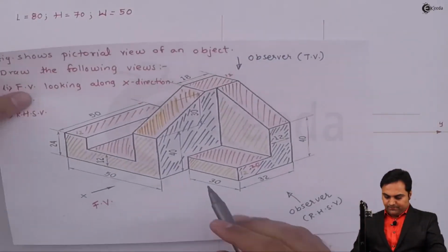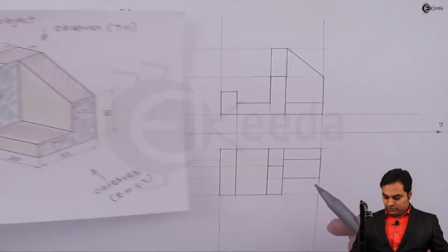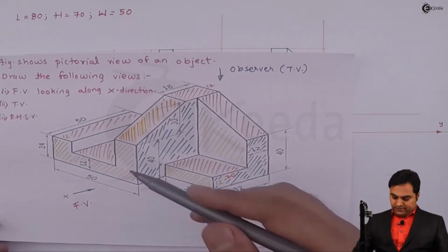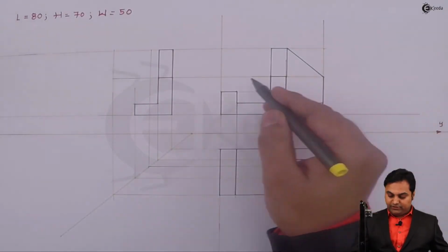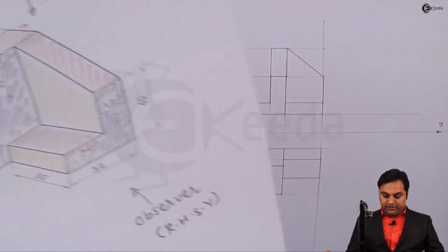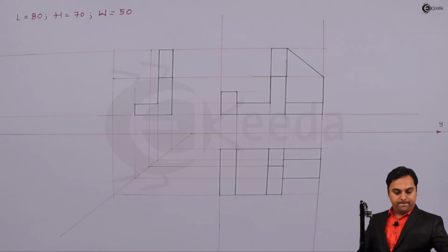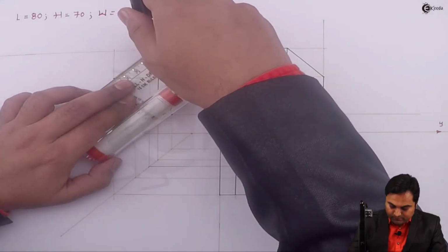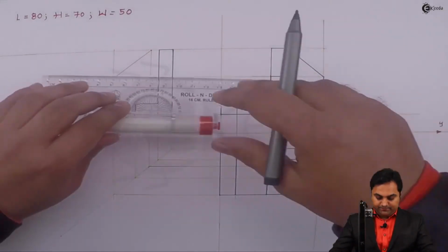I have projected this surface which is of 18 mm width from the top view into the side view, and it will be connected at a distance of 40 mm height from one side. So that 40 mm height we already have. So I have to just connect these 2 points in order to get this inclined surface. And then joining them.